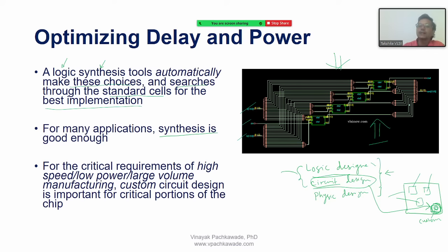want. After that, they will apply and invoke another set of tool, which is a synthesis tool. Then that tool will take the netlist from the compiler tool and automatically generate this figure. So the library of these functions to do this task is already defined in their tools. It's already installed. For example, they are using the 22 nanometer technology in which they want to implement this logic. Okay, that will be the technology library file, whether it will be 20 nanometer or 5 nanometer.